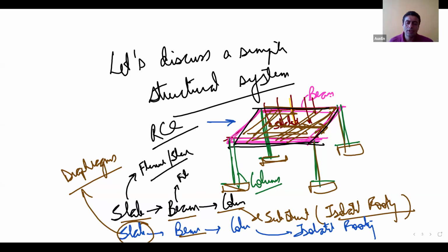It is going to be flexure, shear, torsion maybe. Axial, is it going to be a big problem? Although because of portal action, axial forces do come in beams also, but usually they are not a major cause of concern for us. Understood? So beams have to mainly take flexure, shear, torsion.